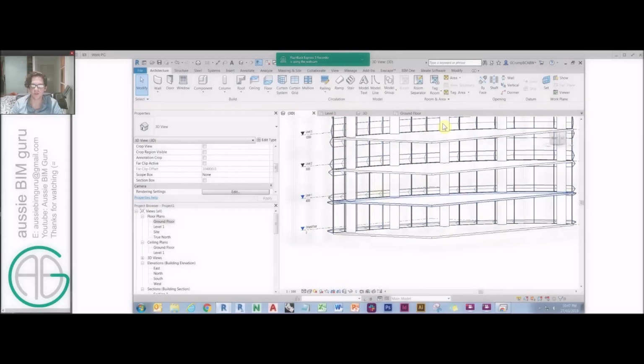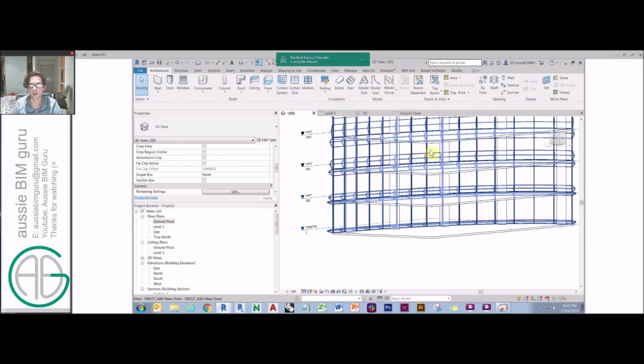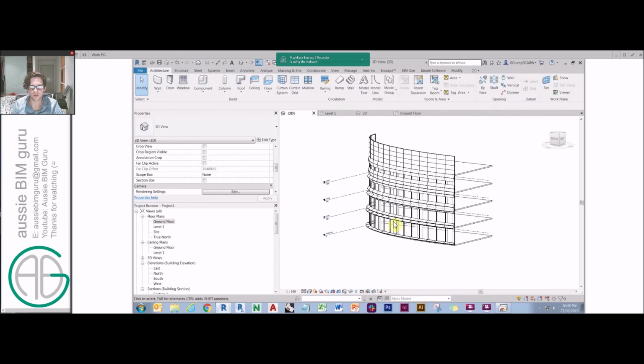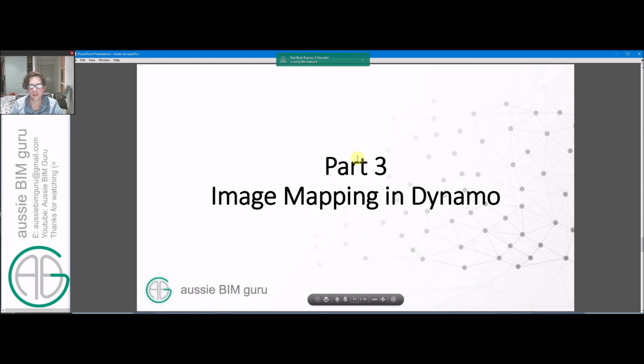There's actually ways to control these panels in Dynamo without using a divided surface as well, using a package called Lunchbox. I'll probably cover that in my next session briefly, because I find Lunchbox can be easier to work with than divided surfaces, and also a lot faster too. But in principle, that's pretty much the tutorial. So I'll just go back to the presentation. So the next session we're going to be running through is how to map an image onto that facade for a driver as the solar heat behavior, so that the panels can basically respond to a solar heat.